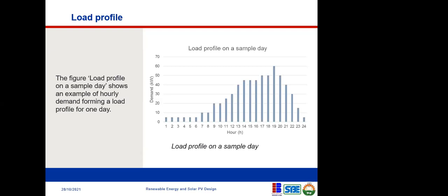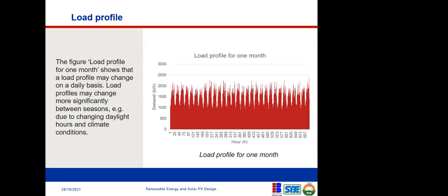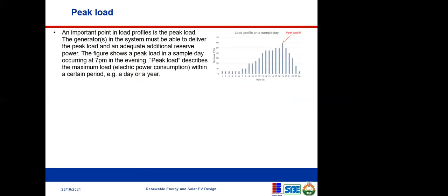So this is a load profile. This is just a sample of a load profile. You can see from morning time up to the evening time when you have your peak, and it begins to die down again to here. It is very, very important when you want to do a solar project to understand how this person consumes power, so that way you know how to size your system. Now this is a load profile, but this is a year's load. Is it? I think okay, it's a one month load profile. You can see it has a lot of data that is clustered together.